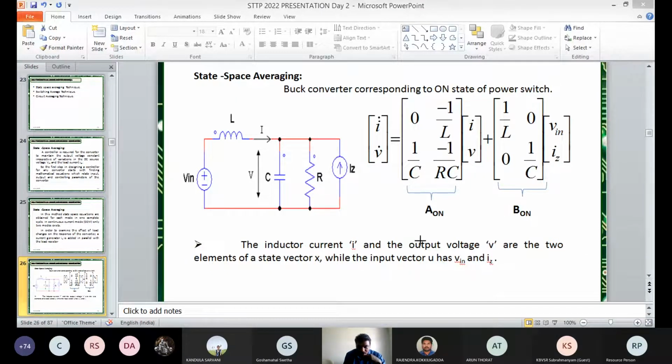So where I am choosing V as the state variable, in the second equation I am getting the derivative for that. Therefore dVc/dt = IL/C - V/RC. So this is the first equation, dIL/dt = Vin/L - V/L. This is the second equation, dVc/dt = IL/C - V/RC.